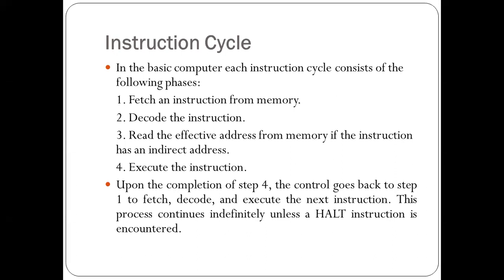Next, execution is nothing but loading the contents of input onto the accumulator. If it is an output type of instruction, then it copies the contents of the accumulator onto the output device. So either thing has to happen. Earlier it may take 4 steps, but either in register reference or IO reference, it will take just 3 steps. These steps have to be completed for every instruction.